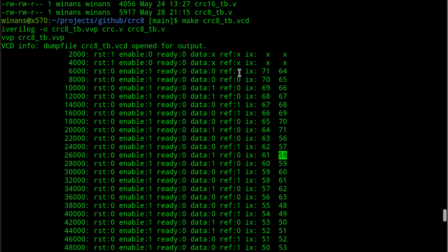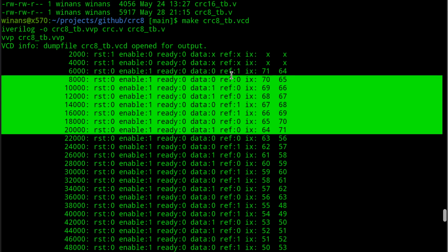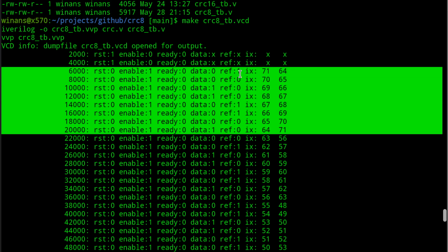And if you're bringing in something like RS-232, a UART style thing, you're going to get the least significant bit first, and then you're going to get the most significant bit. Okay? I'm doing this backwards. There's the 1 from the 31. There you go. This is it right here. There's a 31 in little endian order, and there it is in big endian order. So what would happen is if you had a sequence of bits that were flipped, you don't want to read them in this way and then process the message in the other way.